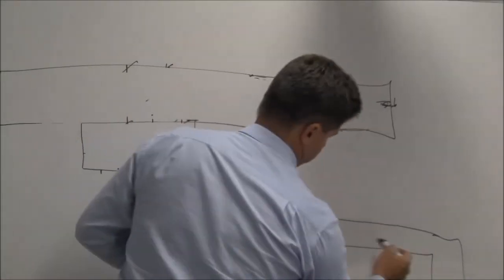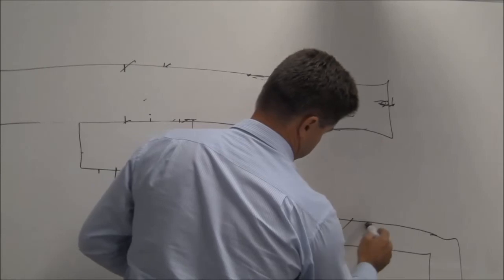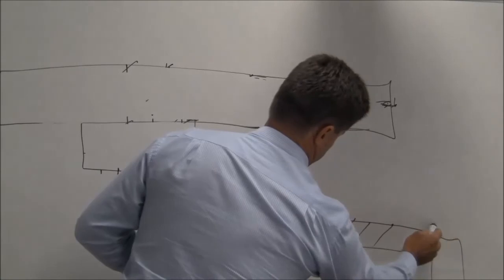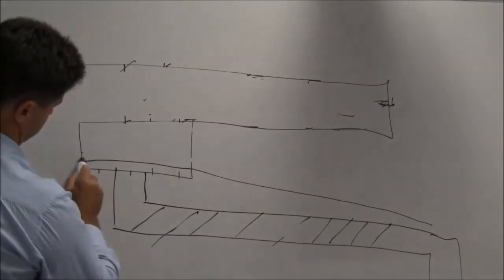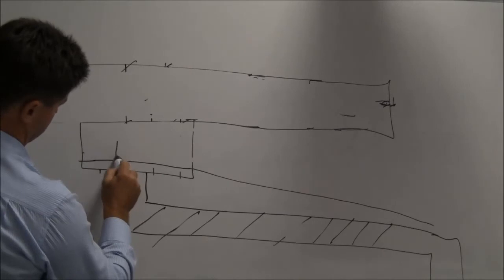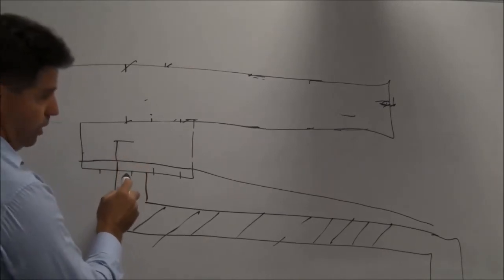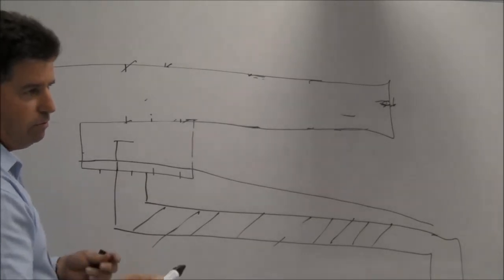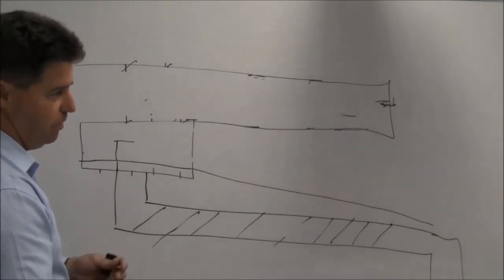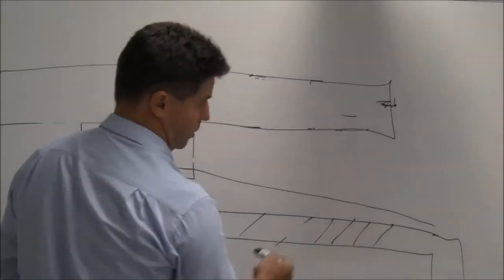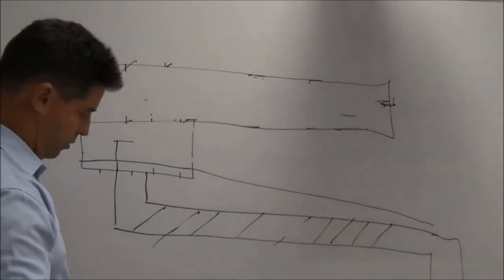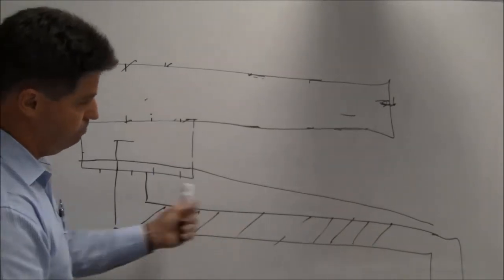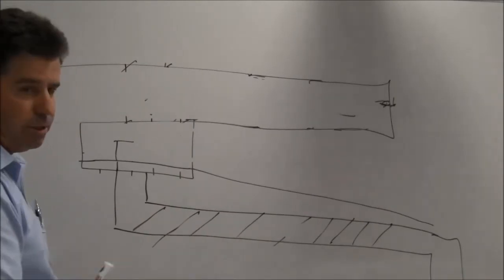So if this pipe is running completely chocker full, right through, the losses in there may come up somewhere up here. You've only calculated your head of water from here to whatever. You've now got to calculate head of water over the top of those losses as well. And I actually have seen that on a job where they've done that same thing. They haven't calculated the losses in the pipe, and the actual box gutter did overflow inside. It was substantial damage, and it was only because they didn't calculate the losses in that pipe system.